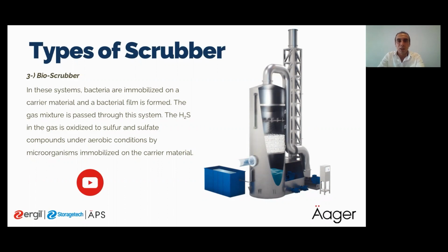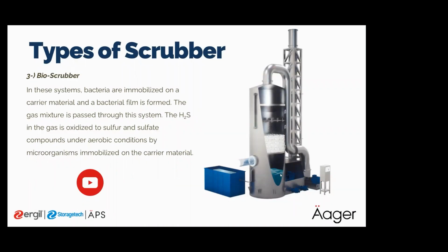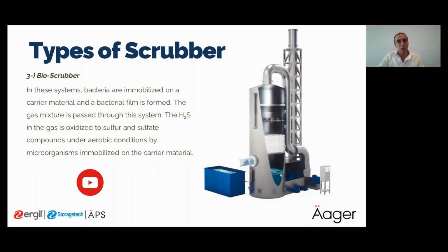But the scrubber cannot be used as heat recovery, because you have a chemical reaction, with a solvent solution from the downside, and you have to reduce the temperature because of the chemical reaction. But most companies use a heat exchanger before the scrubber, and then get heat from the exhaust gas.